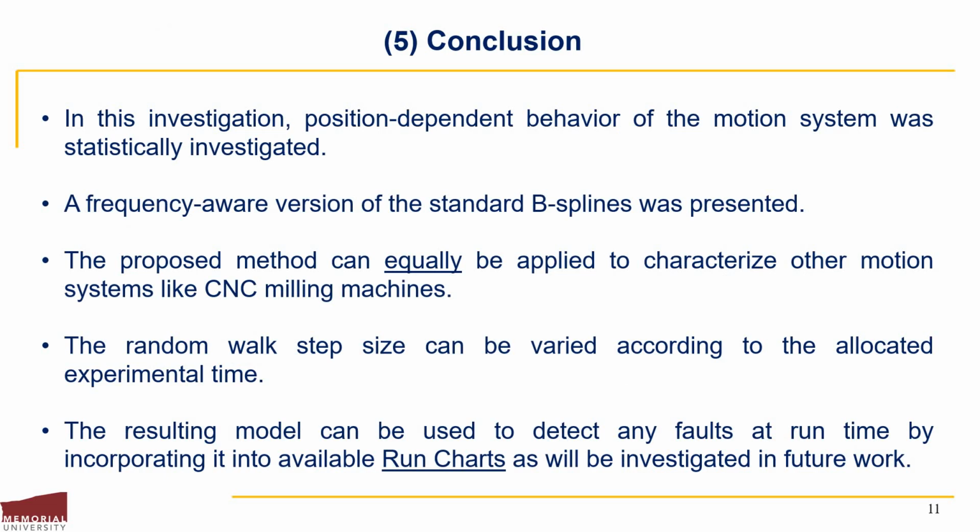In conclusion, the position-dependent behavior of the motion system was statistically investigated in this study, where a frequency-aware version of the standard B-Splines was presented. The proposed method can also be applied to characterize other motion systems, like CNC milling machines, for example, where the random walk step size can be varied according to the allocated experimental time. The resulting model can be used to detect any faults at runtime by incorporating it into available run charts, as will be investigated in future work.